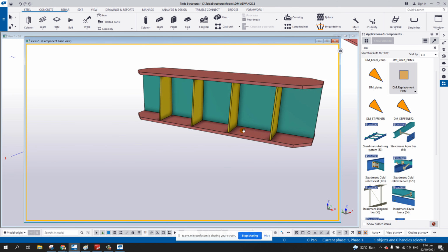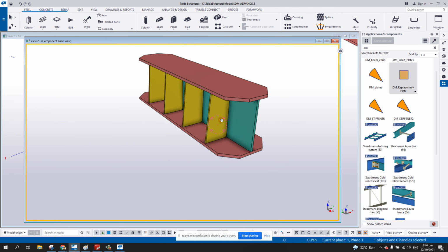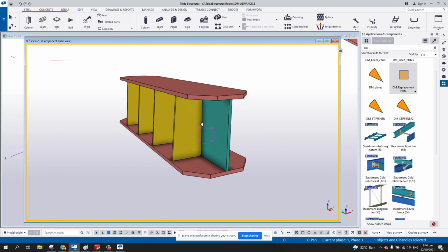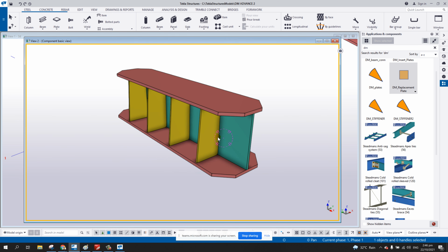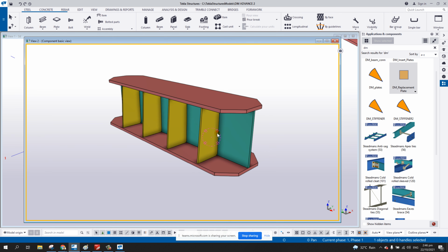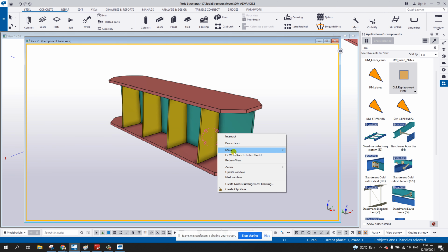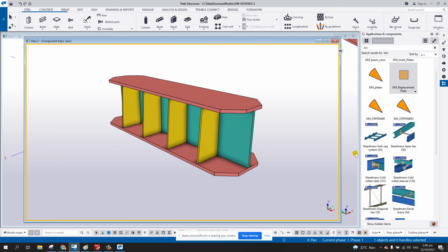So all you have to do is make a view like this, and then shift, control, and right click, redraw, so that you will remove this symbol. Yes, and then now you can create a PNG file or JPEG file.